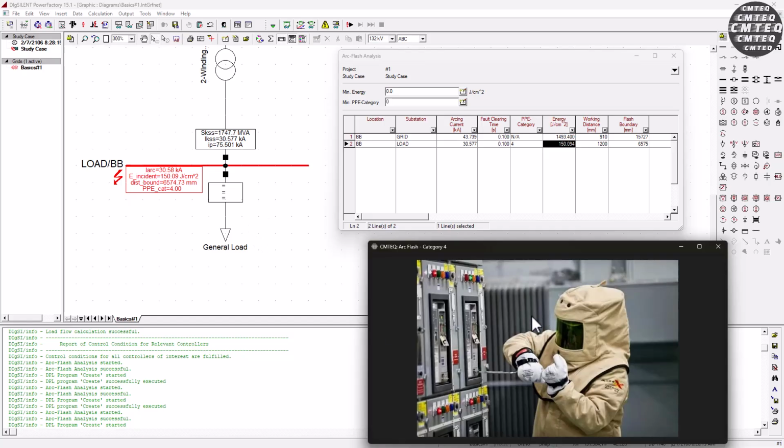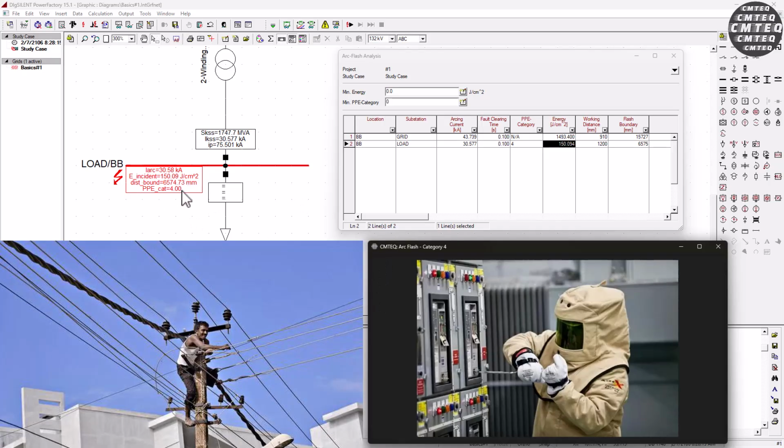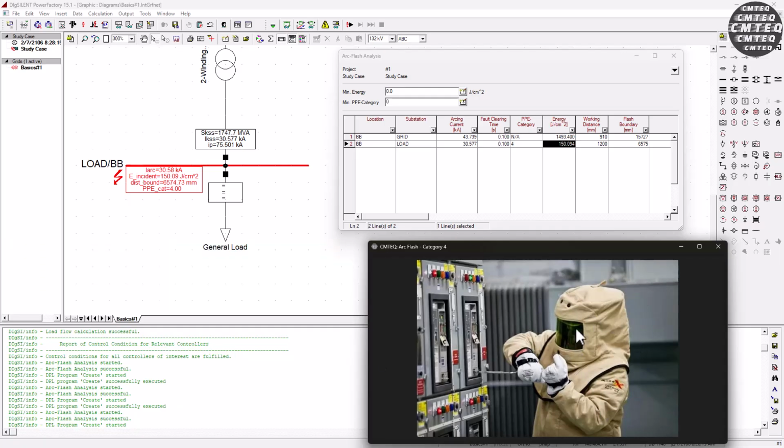So this places you right within a second degree burn based on that working distance of 6.6 meters. So that basically means anyone who attempts to come closer within this distance without proper protection, like a full rated suit here, is going to sustain burn injuries.